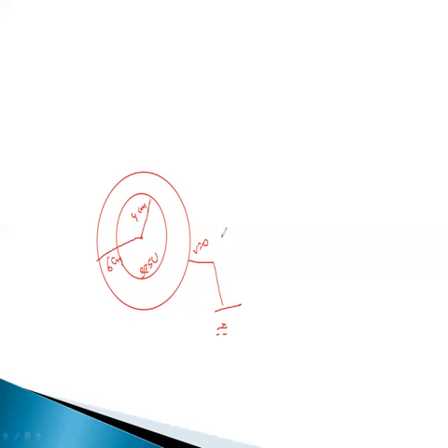Okay, now to calculate the potential on the inner sphere, for example, if Q is the charge on the inner sphere which you have to calculate, then what will be the charge on the outer sphere? Because of induction, minus Q charge will be induced on the inner part of the outer surface. Hence, what is the potential due to this particular sphere at the same point on the surface?